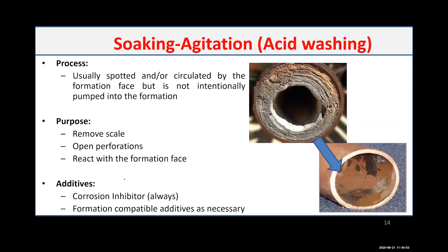The second one is what we call soaking or acid washing. Here we would like to merely clean the tubing from scale. I have here a picture of a calcium carbonate scale. You can see this is the tube part, and all this thickness is actually scale.